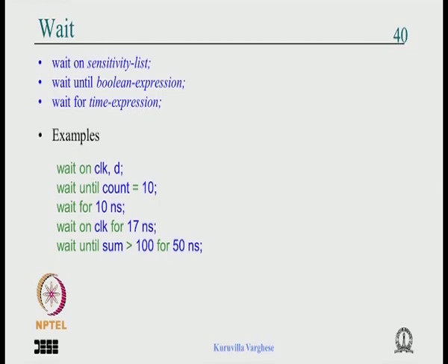You can combine these wait on and wait until with the for clause. Here, wait on clock for 17 nanosecond can be used for simulation. It means wait for an event on clock, or 17 nanosecond. If there is an event on the clock, continue; otherwise, till 17 nanosecond the simulator waits for an event, and then it continues.